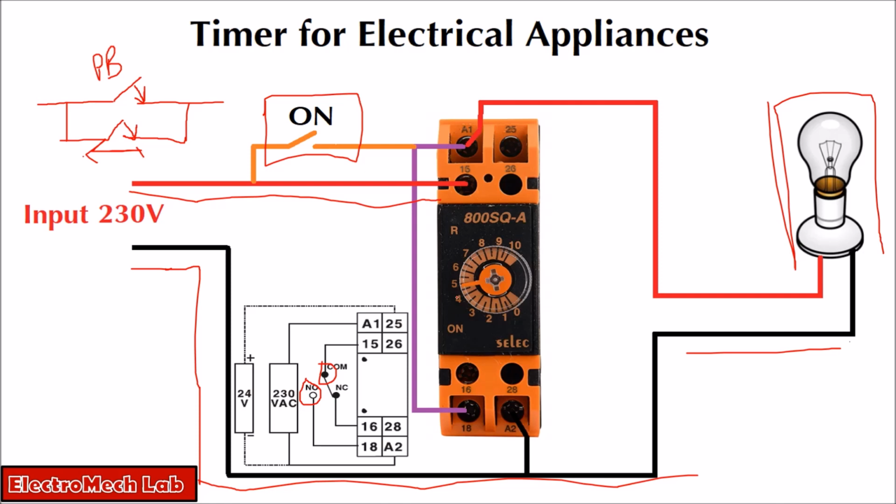In our case that is 5 seconds. So basically, with the help of pushing this push button, we are latching this timer for the time which we have set on this timer with the help of this dial. There might be some difficulty understanding for some users, but if you see this video 2 or 3 times, I think after that you will get what I want to convey to you.